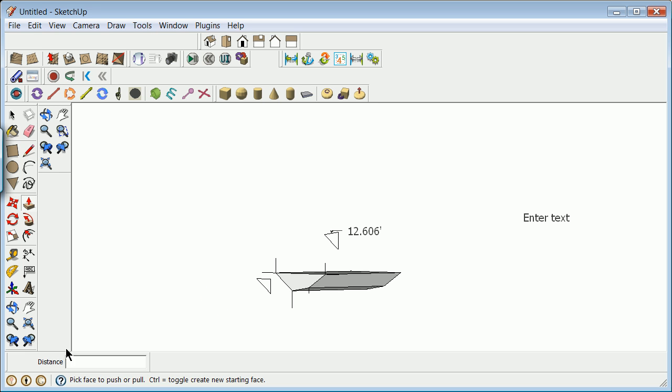So that's just a quick one-off on how you go about using graphics to do the cables. As a review, what we did was we solved for the reactions in the y direction. We used the geometry of one side's cable as it was given. We have to have one point to solve what the reaction in the horizontal direction is, and we put that to both sides, and then we use the geometry of the cable system to figure out where the other points are. That will work with more than one or two forces. You can do that with a series of things on a cable, and you start to approximate the catenary or the parabola as you do a lot more. Thanks for listening. That'll be the last post in how to do cables.